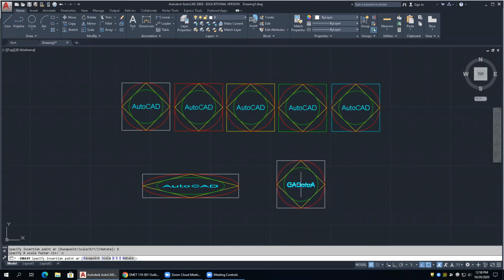And notice now when you enter that block, it rotated it in the X direction about the Y axis. Notice it's mirrored. So I could mirror it in X, I could mirror it in Y. Why that's important is because, for instance, if you're drawing doors, some doors open left, some doors open right. You don't have to create 2 models. You can create 1 model and just mirror it to be whatever condition that you need.